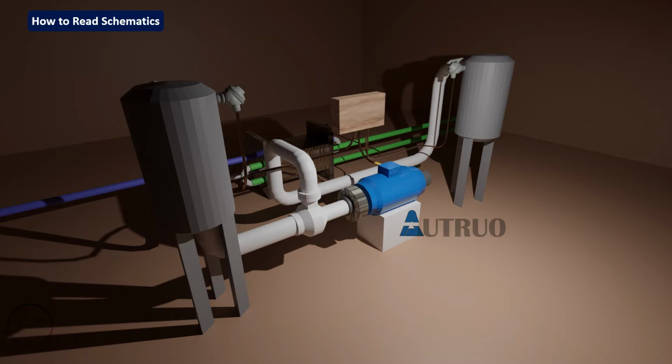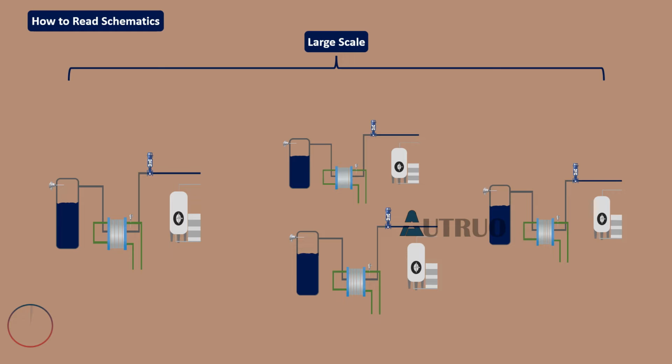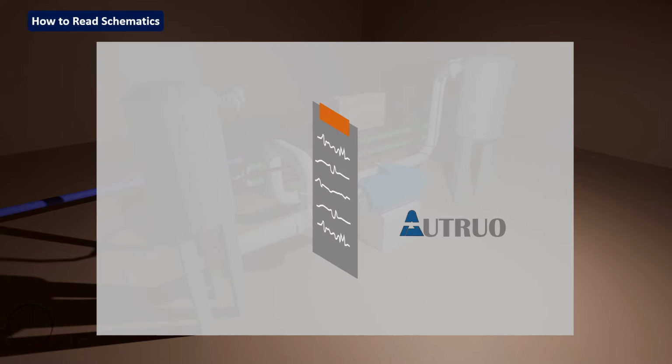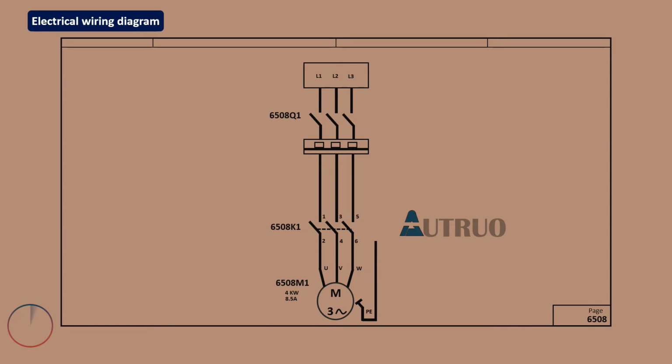In a complex automated setup, machine vendors have devised a perfect way of understanding this complex termination at the operator end. Because as more variants of these machines or process equipment are produced at a large scale, there is a need for documentation which will provide a comprehensive description of how the cables are terminated to the programmable logic controller, also known as PLC. This document describes the cable terminations, voltage and current rating of all the interconnected devices. So let's look at a typical example.